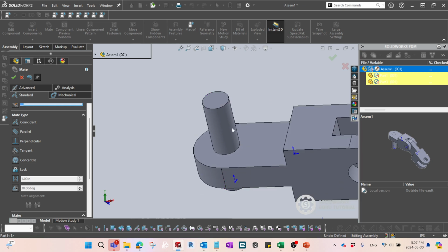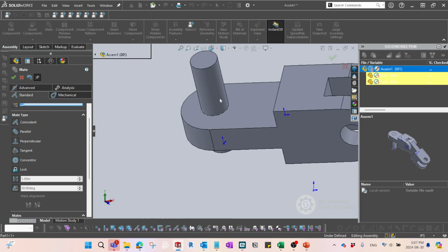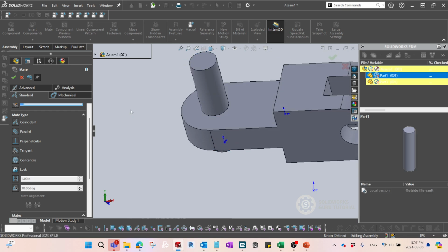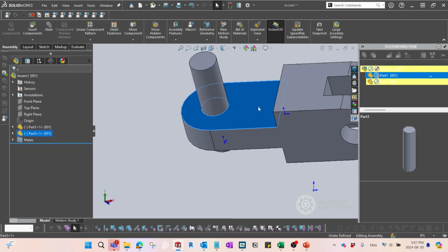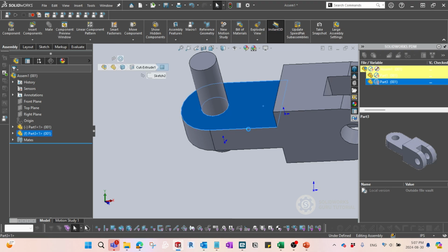It's a little bit hard to see whether or not this is rotating, but if you carefully have a look at this origin, I'm just going to right click it, and then, all right, oh, this is not good. All right, what I'm going to do is just right click this one and fix it so this is not moving at all. So as you can see, there's an F mark. It's a minus mark, which means this is in a fixed state. So it's not going to be moving or rotated.